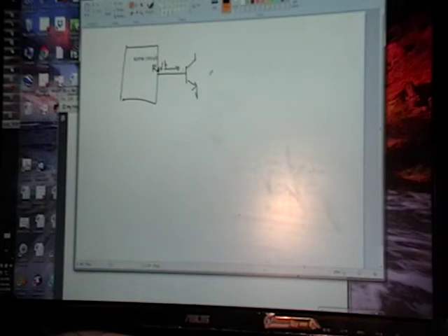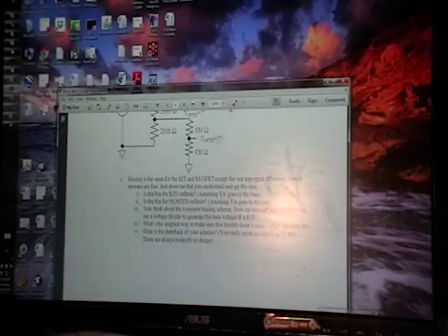And you've seen in the lab handouts some ways to calculate R in. So you need to make that R in much greater than the R out of your circuit, and then you'll be fine. Okay, so that's loading.